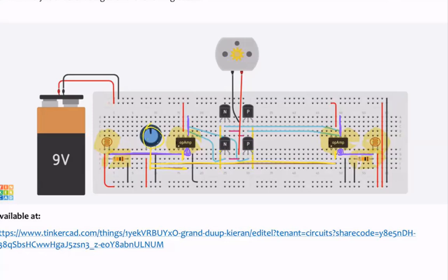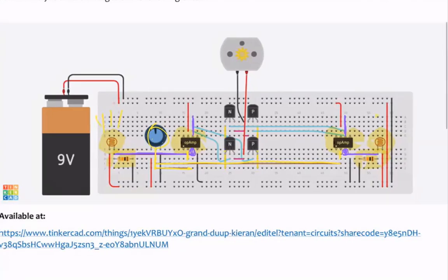When the light falls on the LDR, the voltage at the non-inverting terminal of the corresponding comparator increases. And when that increases, the output of the op-amp goes high. So that is what the op-amps are doing. They're basically working as comparators, looking at the voltages which are dependent upon the light intensity.